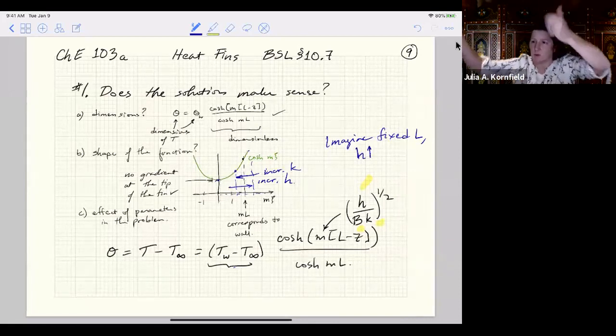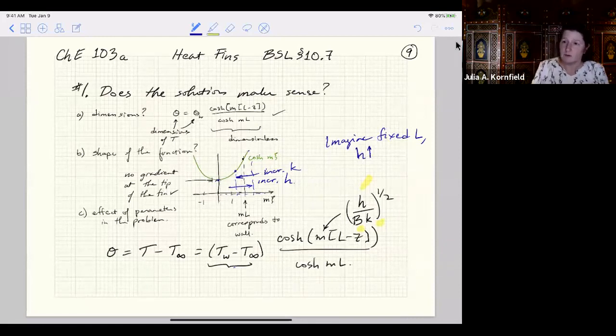And then it's removed from the surfaces of the fin to the fluid. Similar thing happens if you make b a little bit thicker, then it maintains that temperature further out into the fin, and the overall temperature drop goes down, and the actual energy you're removing per area of fin actually goes up.